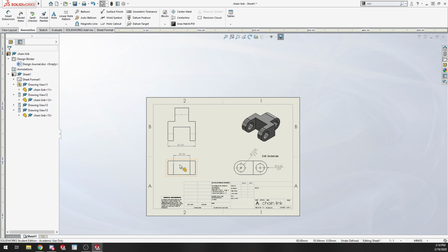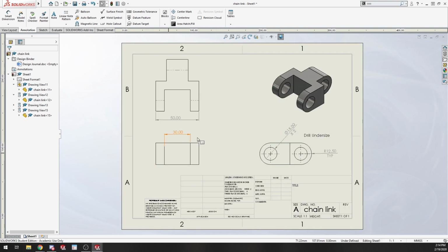But for drawings in the meantime, you're going to go down to the machine shop. Most are going to be using mills, 2-dimensional or 2.5 dimensions. Basically you'll be looking at it from face views. You're not going to need to see too much in 3D. Draw your stuff out. If this is all in millimeters right now, and I'm going down to the machine shop, I want everything in inches, right down here I can switch it over. It does all the unit conversions for me. That way, when I'm looking for an end mill or reading the DROs down there, I know what I need to do.